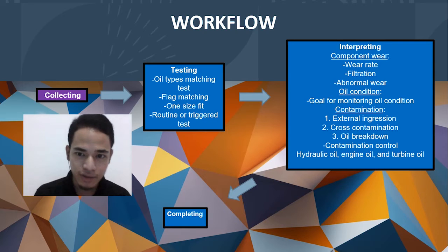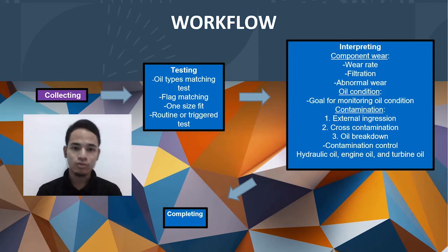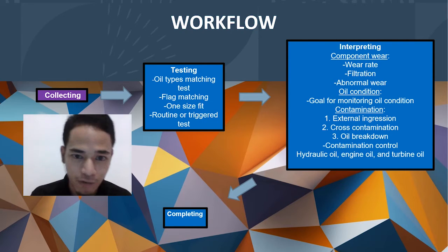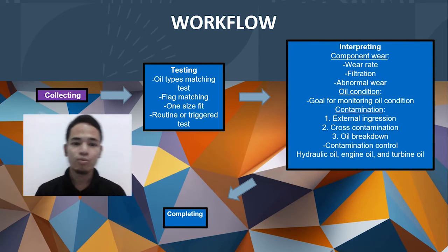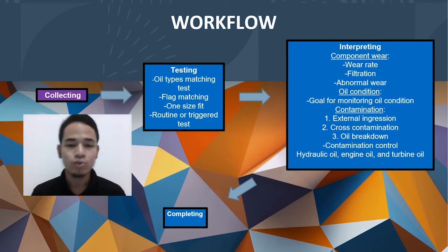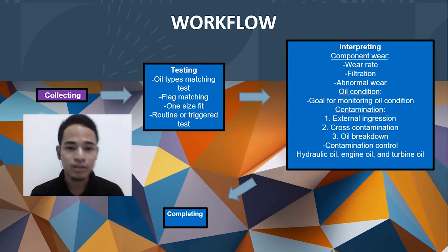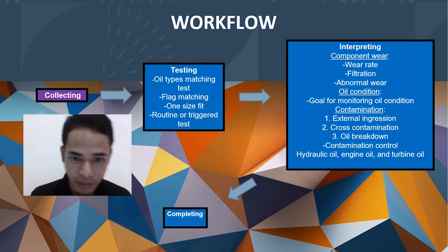The third step is interpreting. By interpreting, we have to consider the identification of actionable work, component wear. By component wear, I mean some component wear is to be expected, and wear rate may increase with age. Filtration may give the impression of steady state wear.